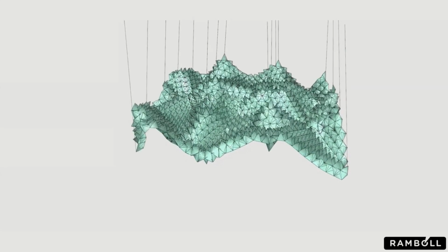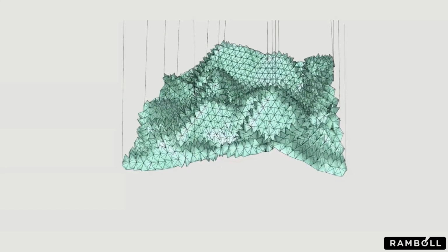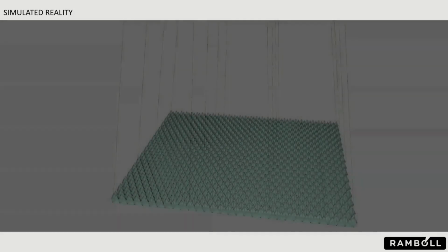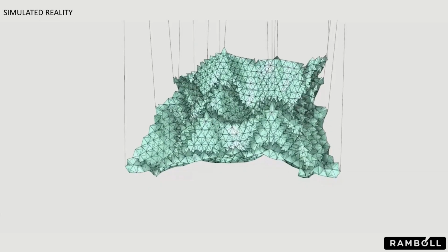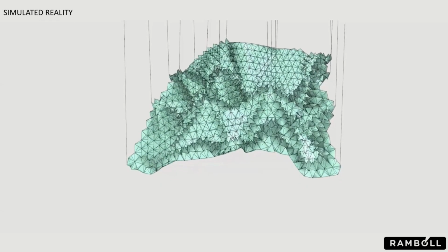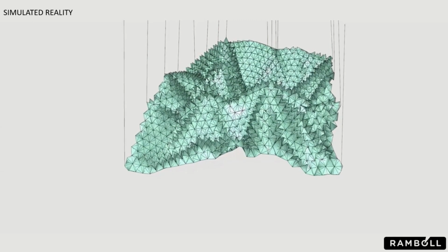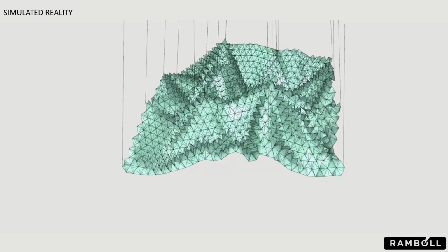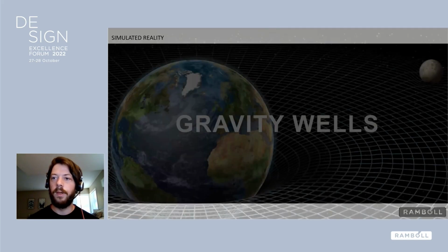We use this simulation to be able to control this very non-linear form found structure, and then once we had a final settled geometry, we were able to export and analyze it, and check the stress at all of the interfaces between a few thousand paper tetrahedral units, or Sonobe units, to confirm that we didn't need to glue them together, that they could hold themselves just by friction.